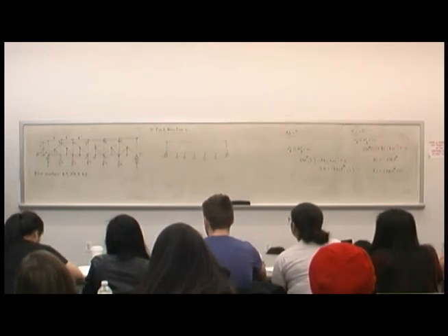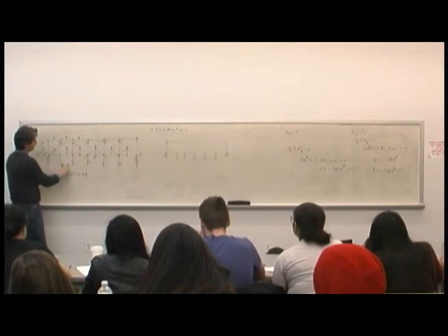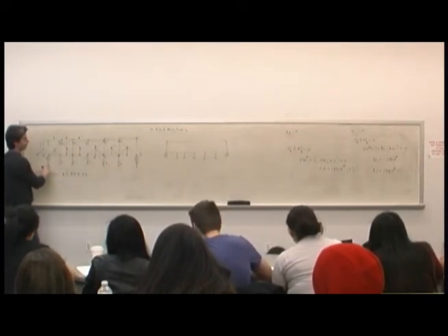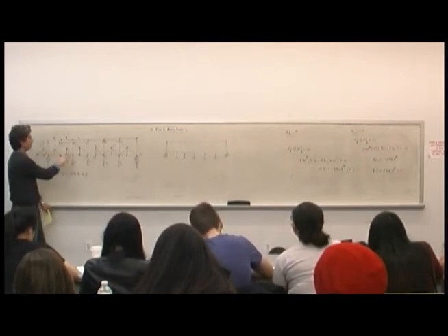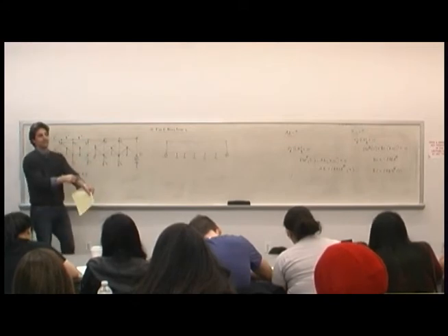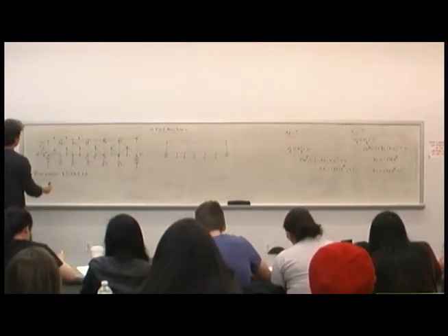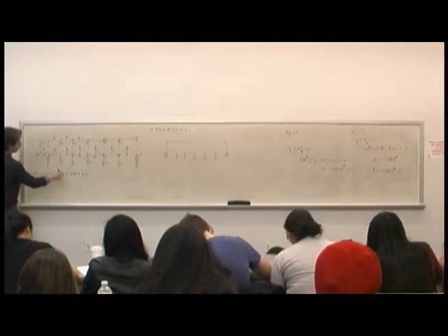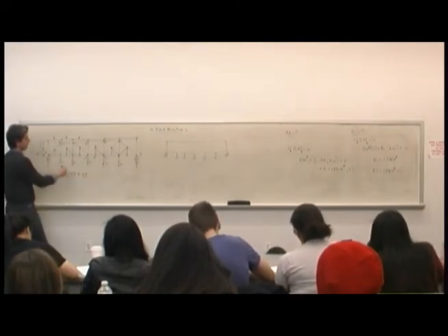Just on the moments. Don't worry about all the truss members. Look at these forces. These are our external forces, and we're looking for the reactions. These external forces are creating the reactions, right? They're also creating the force inside the members, but we'll get to that in a minute. The problem is asking to find the force in these members EF, JK, and HJ, but I still need these reactions. I need this and this.